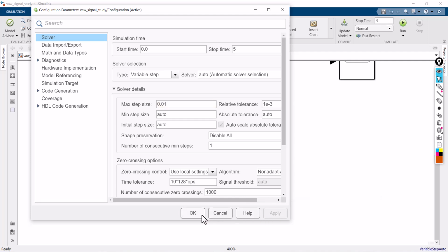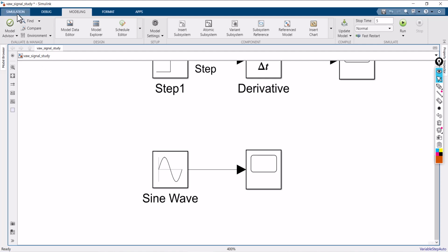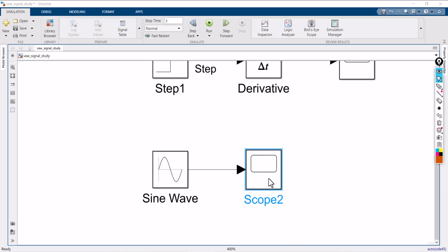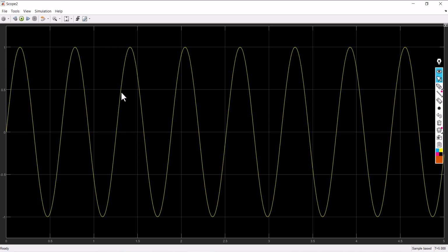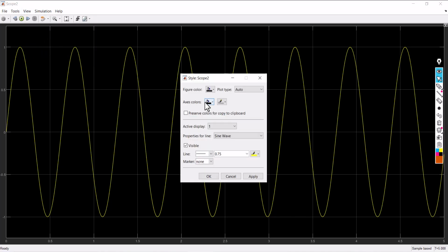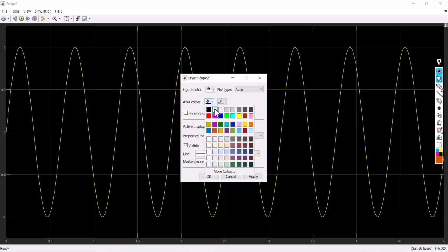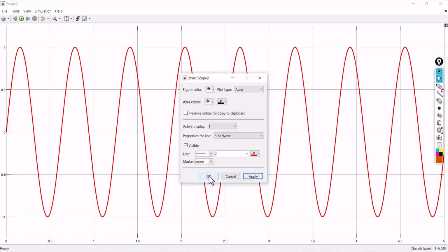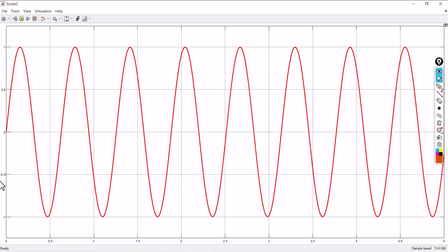So it will increase the number of samples to analyze. Click apply. Now again go back to simulation. Just click the run button. You'll be getting a proper pure sinusoidal waveform. So this is the way you can improvise your response. If you want to see in a clear manner, just go to style, change the background. Make it as some color. You'll be getting a pure output.